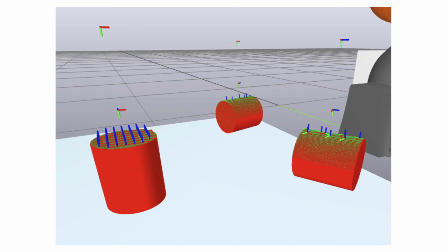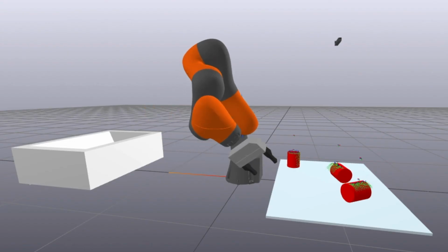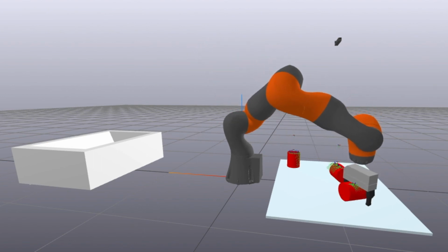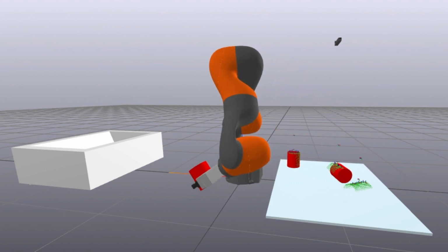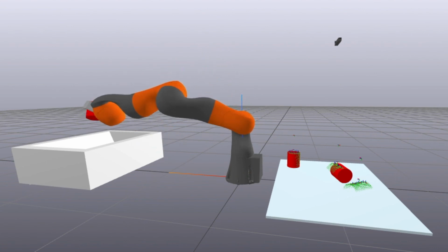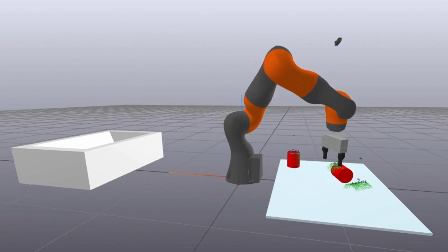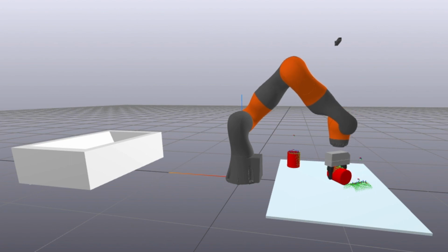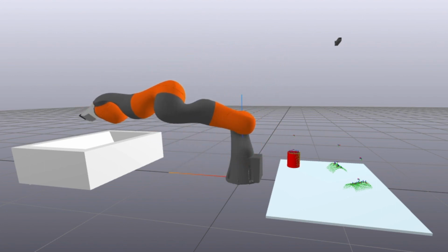And now with all that, we're able to calculate pre-grasp and grasp poses to be fed to our motion planning system. So this is the IIWA in action. The nominal trajectory is defined by dividing up the motion into several time segments from pre-grasp pose to grasp pose to a few waypoints and back. Between any two poses, the IIWA linearly interpolates the translation and rotation. It is similar to the door opening problem in set 5 in that our algorithm also does optimization-based inverse kinematics, converting the end effector trajectory into a joint space trajectory using a mathematical program to solve for the optimization.